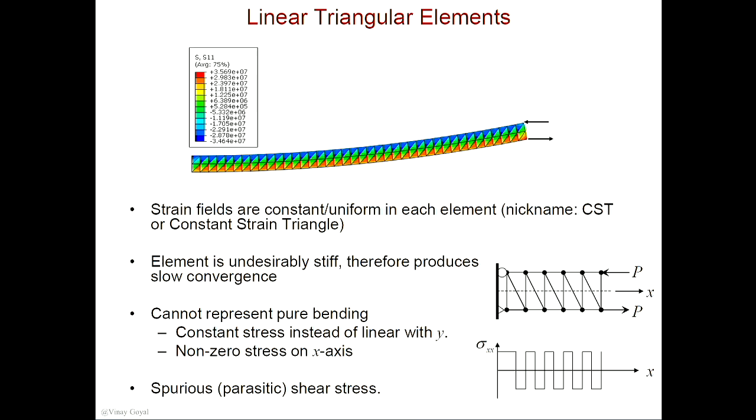Some notes I want to cover really quick: if I were to take triangular elements, and thank you Leonardo for this, mesh this and apply loading, I'll have oscillations that go from positive to negative back and forth. And if I had a single element, it would be even worse. You'll see that in your homework, because your homework was done on purpose so you can get something like that, positive, negative. Why is that happening?